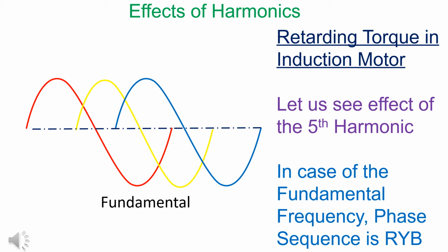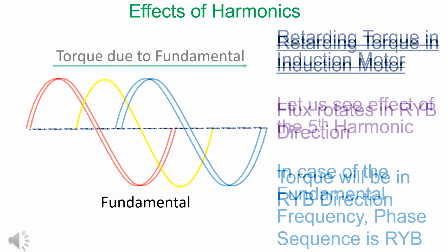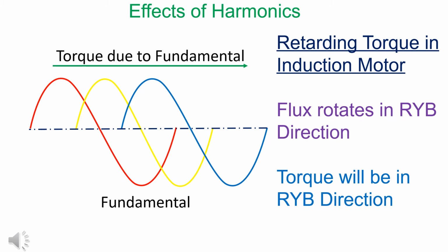Let us see the effect of the fifth harmonic on the induction motor. Phase sequence in the case of the fundamental frequency is RYB. In the case of the fundamental frequency, flux rotates in the RYB direction. Hence, torque will be in the RYB direction.